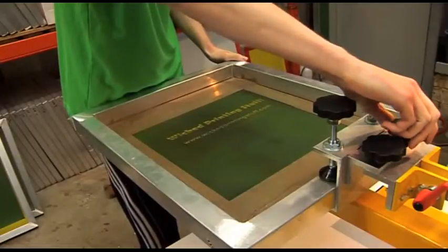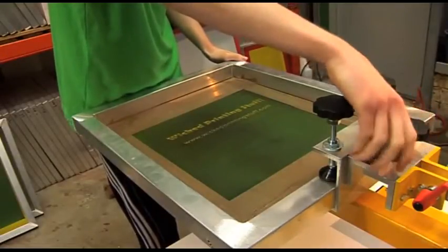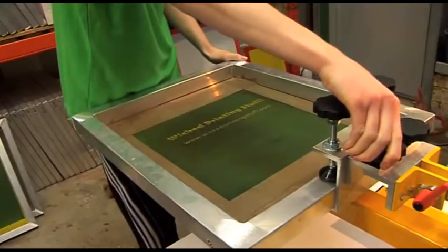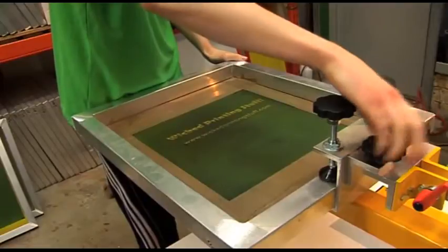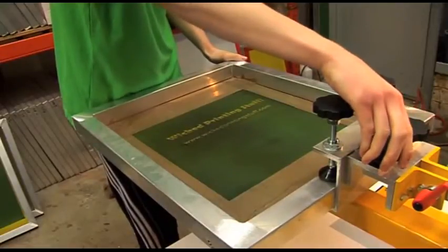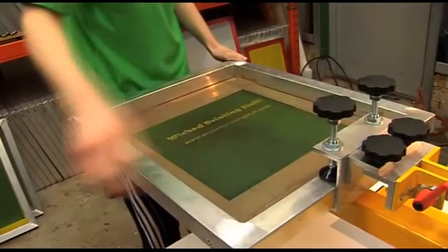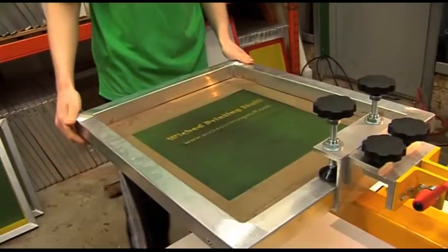If you're printing with a Wicked Printing Stuff press, in order to achieve micro-registration, enabling each colour of your design to line up exactly with the next, adjust the second set of hand wheels to move the entire clamp head to any angle and position you desire. That leads us back onto today's print.